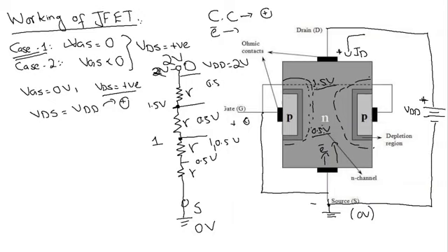Now we know from the diode discussion that the reverse biased voltage increases the width of the depletion region. So more the diode is reverse biased, the wider is the depletion region. Now here the diode is reverse biased by 1.5 volt, so the depletion region will be wider here as compared to here which is reverse biased by 0.5 volt. So that is why as we move upward,